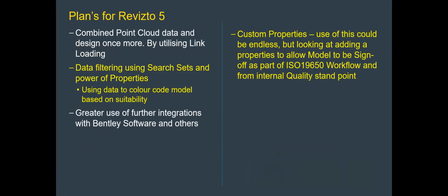And finally, what am I planning for Revizto 5? So again, combining the point cloud data so we don't have these disjointed between existing and proposed information. Data filtering using the save search sets and the power of the properties, and using the data visibility tools to change the color depending on what is the suitability of the model, what am I asking it, and then obviously using greater use of the further integrations that Revizto have gone with Bentley software and with others.